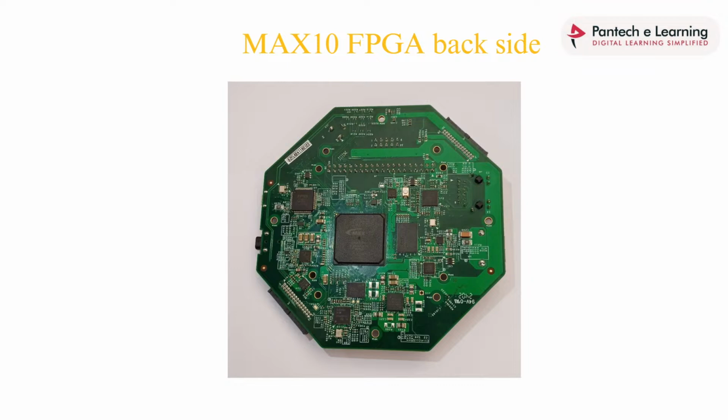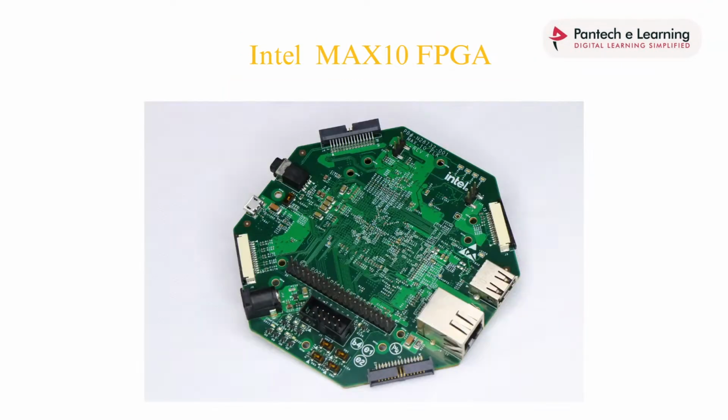Xilinx is owned by AMD. AMD is giving the Spartan boards, so AMD gives a separate tool for their FPGAs, like Xilinx and Vivado. By using the tools only we can program, but this is a Max 10 FPGA board. We can't use Xilinx to dump the code into this FPGA. We have to use only the Intel Quartus Prime tool to reconfigure this FPGA.